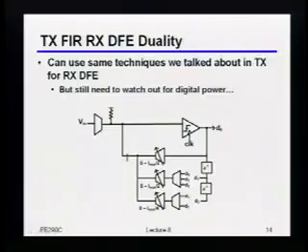The only thing you should keep in mind, which I reminded you of on the transmit side as well, is that any of these tricks that you play is always a trade-off between how much parasitic cap is on this node and how much power you spend in the digital stuff in front of it to support all of these different configurations or logic that you're doing on it, right? And again, in the limit, you'd have a big digital signal processor here that would generate some number of bits, and then you'd feed it into a DAC, right? That would be the minimum parasitic capacitance you can get, but the maximum amount of digital power that you could be spending. Yeah? So that also adds digital delay, right?